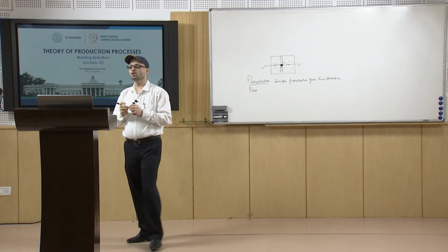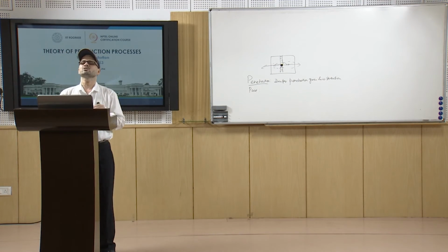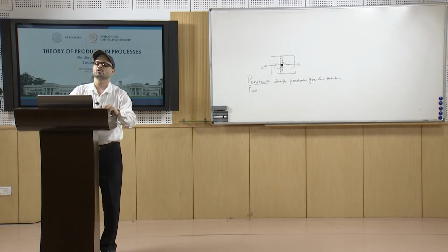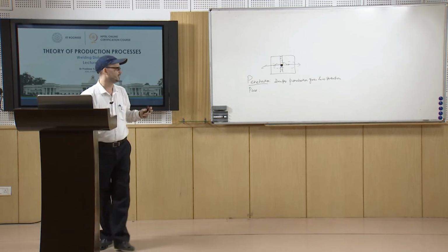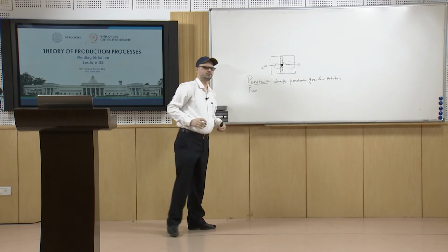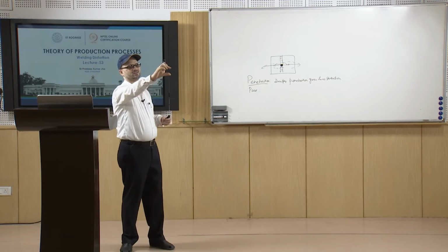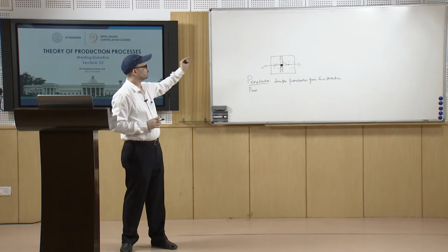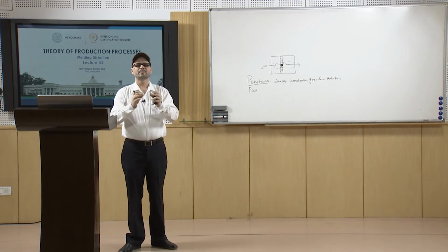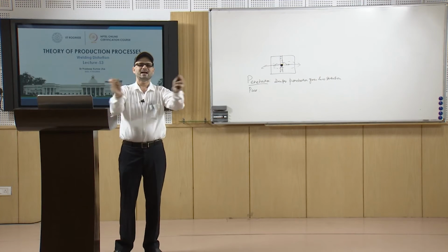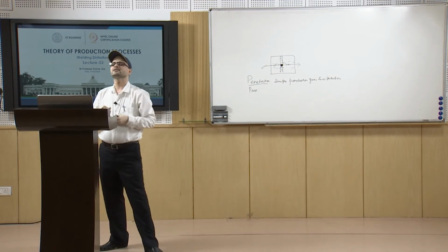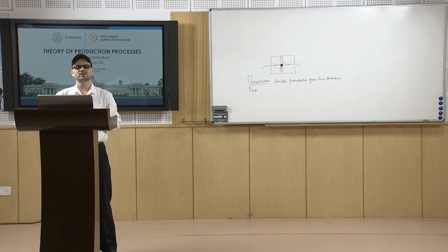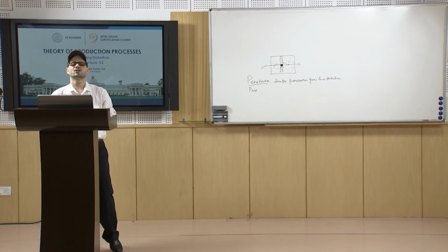So, the way you go, you may go fast or you may go slow. Based on that and depending upon the heat input also, you have these two sides. Many a times when you are welding larger sections or larger plates, and you are not putting the tack welds, you can see that when you reach towards the end, either they are separated apart or they may go like this. So, you have to again pull it and then do the welding. That is the example of the rotational distortion. So, this is about the rotational distortion.